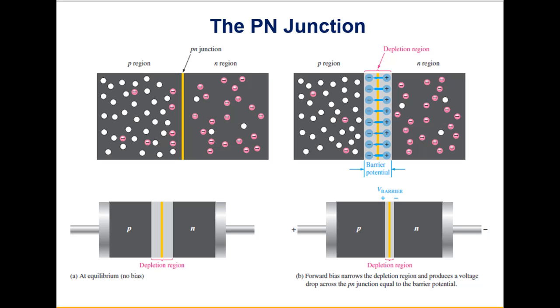In reverse bias, DC voltage is applied through the diode in the opposite direction. At first, this causes the depletion region to widen and no current can flow. Once the reverse voltage is increased to a high enough value, the reverse current flow will substantially increase. This voltage value is known as breakdown voltage.